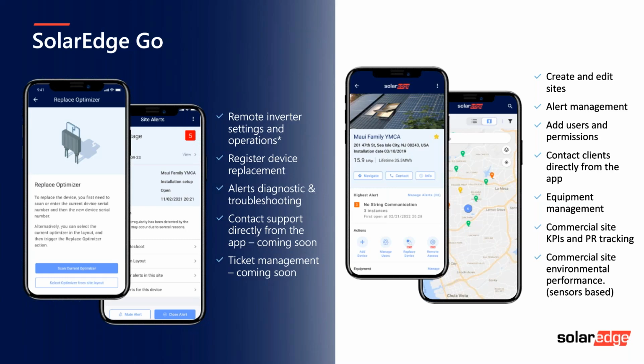So if you just think about that practically, you can install the system, set it up to do the firmware updates, and leave site. You can then that night or the next morning jump back into the system and finish off the commissioning, because sometimes firmware updates might take half hour, 45 minutes or whatever, and you just want to get off, or it could be the end of the day and there isn't enough PV generation to kick in all the optimizers to do the pairing. So it is an absolute game changer for us, SolarEdge Go.